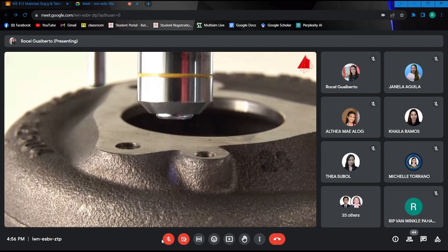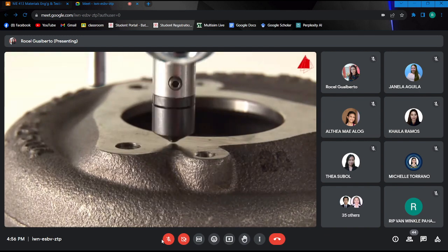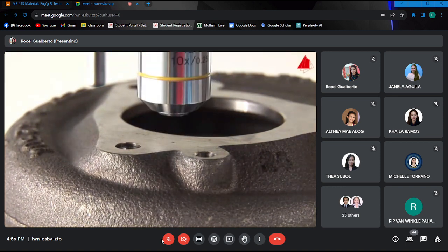The testing machine rotates the lens back to its resting position and places the spherical indenter carefully on the test piece surface. Gradually and shock-free, the test force rises to its specified value. After maintaining the test force for a certain time, the indenter automatically lifts off again and the microscope lens pans back to its former position.